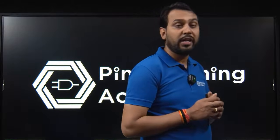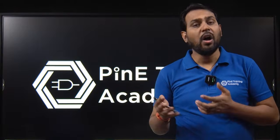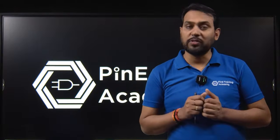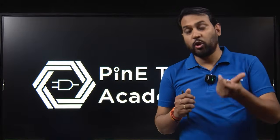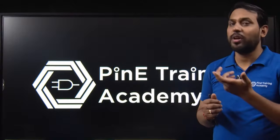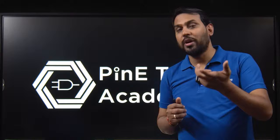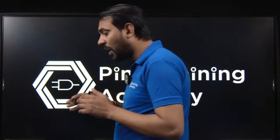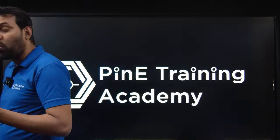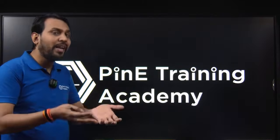In the second lecture, we discussed that you can design a fixed resistor with the help of polysilicon, or you can design it with the help of a MOSFET. It depends on your application. If you want a tunable, voltage-controlled resistor, you can use a MOSFET. If you want a voltage-controlled capacitor, you can use a MOSCAP. We cannot design an inductor from the MOSFET because a MOSFET does not have any coil. It does not have the property of storing a magnetic field.